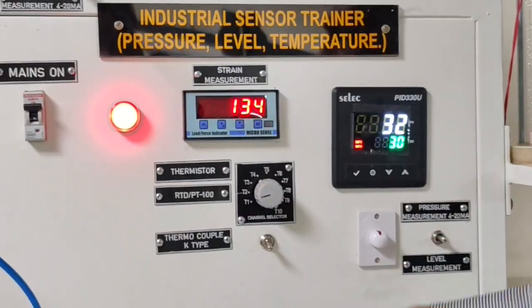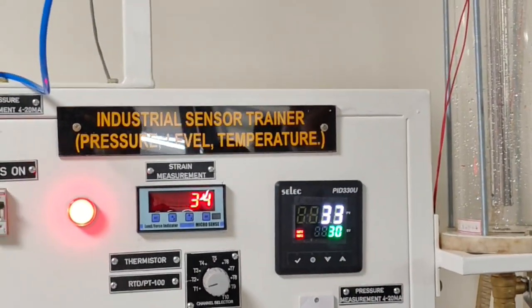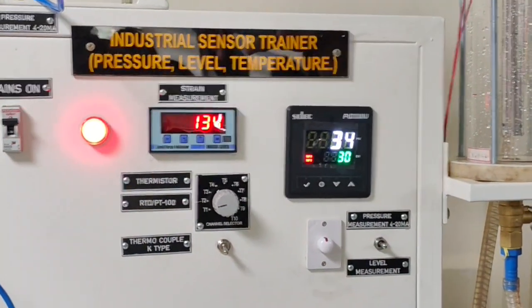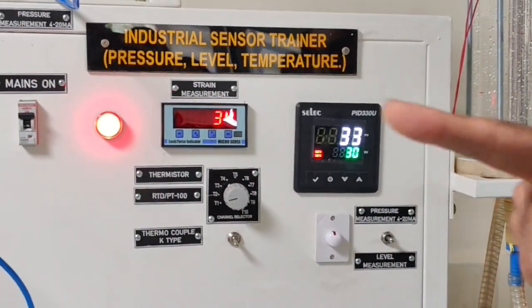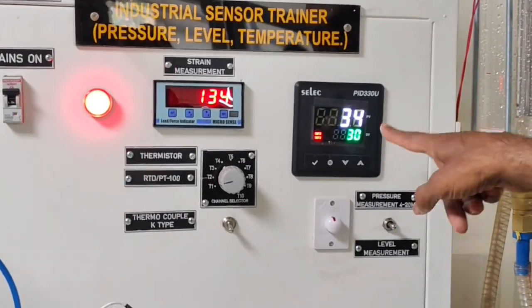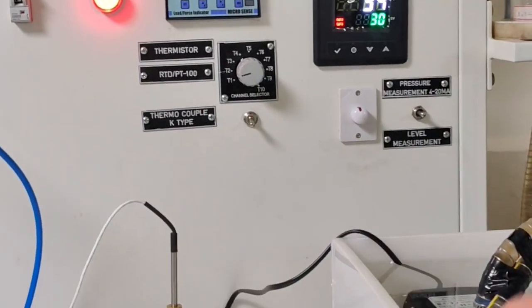Here certain millivolts is generated. That millivolts maybe around 0.1 or 1.2 something millivolt. That is equivalent to 33 degree. K-type temperature, you have the millivolts versus temperature chart. Sir, I think you must be knowing that. Temperature versus millivolts are readily available. For particular temperature, what is the millivolt you can see. With the multimeter also you can check it up. In Google also you will get it.